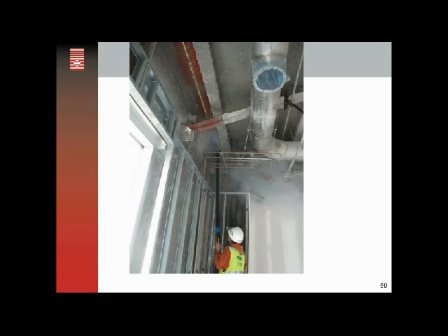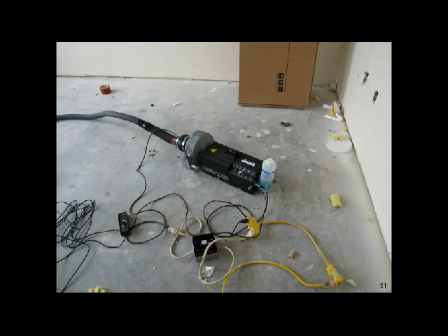And here's a shot of Terry Brennan, a building scientist working on a commercial building. He's got the building depressurized, and Terry uses a vacuum cleaner extension pole, and he is fogging what looks like the roof wall juncture of a building. If he sees air movement, he knows he's got an air leak. This is Terry's rig. Again, it's a theatrical fogger with a booster fan on a vacuum cleaner hose and some controls that he's put together.